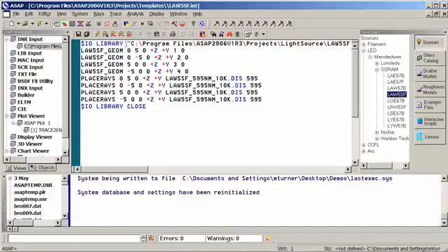ASAP will open the library to go to the ASAP directory that has the information about the physical model of the source, and it will place that geometry at 4 separate locations, and it will also place the ray sets at those locations. What this allows me to do is to either choose to include or not include the geometry when I'm doing my ray trace and analysis. But to make sure I get the proper analysis in the end to take into account any near-field effects, I would want to make sure that geometry is properly positioned.